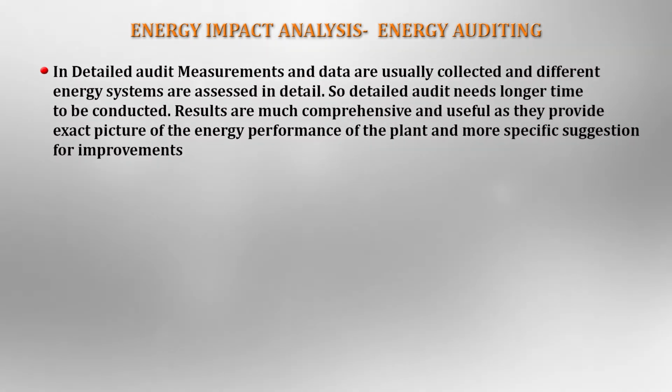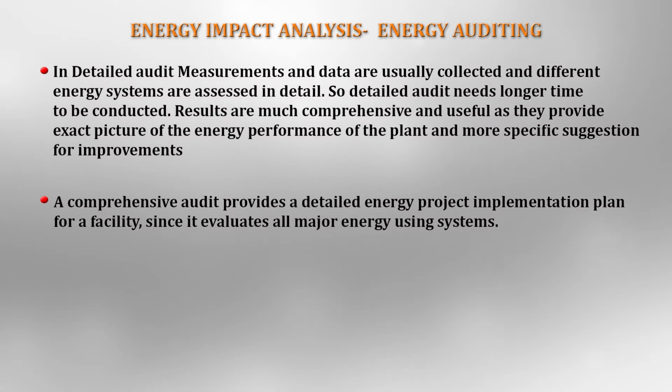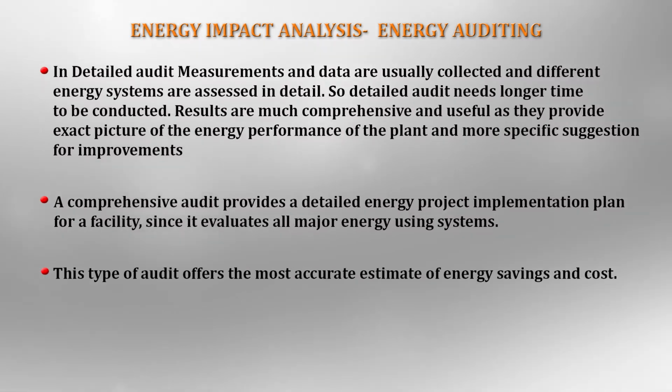specific suggestions for improvements. A comprehensive audit provides a detailed energy project implementation plan for a facility since it evaluates all major energy using systems. This type of audit offers the most accurate estimate of energy saving and cost. It considers the interactive effects of all projects, accounts for the energy use of all major equipment, and it includes detailed energy cost saving calculation and project cost.